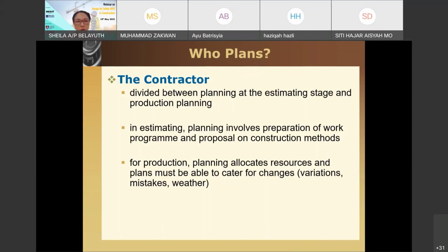Okay, so if it's too crowded, for example, but it's needed, but it's too crowded, maybe you might want to enlarge the column just to ensure that the honeycomb will not be produced that badly. Because sometimes when we design, we might not really reflect on how it will be constructed. So that's one thing about it.